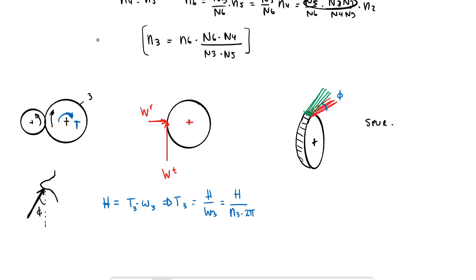Okay, that would give me radians per minute. And then horsepower is usually in horsepower, so I need to multiply that by 33,000 to get pound-feet per minute. Since I usually use, if I do this, I would get pound force as the units for my torque. If I want pound-inches, I would actually be multiplying by 12 inches, so that feet cancels out and I get inches on the top. Okay, so I say all that to say that you can calculate T3.